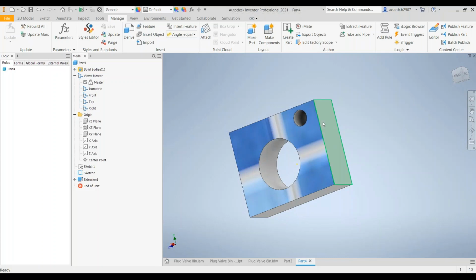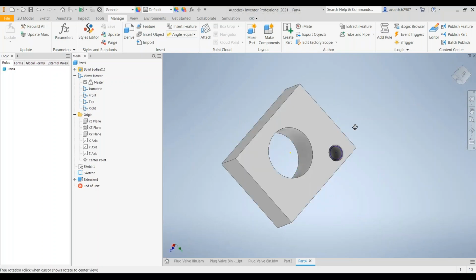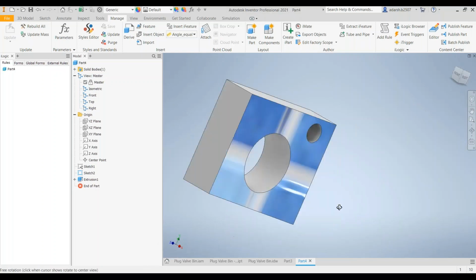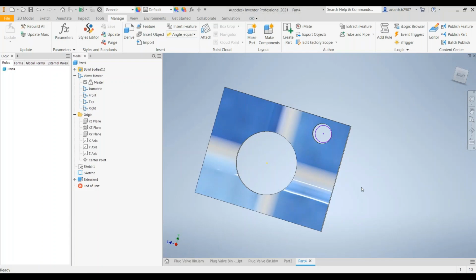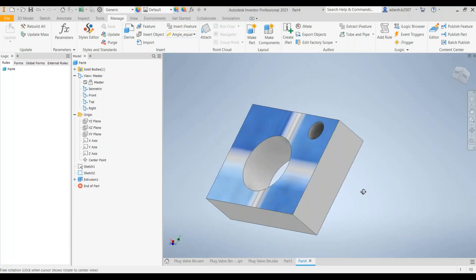So we need three times the, sorry. So if height is 2 centimeter and we need to calculate the breadth, we can do so by keeping it as a parameter, and we can multiply by 2. The whole software would multiply by 2 and add that parameter to our model, creating a parametric model. So we add certain parameters to help make this model.